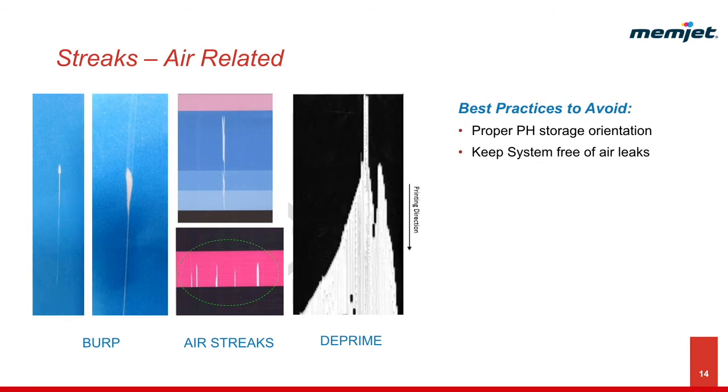When the printhead is stored either nozzle up or if the box is in an upright position, the fluid drains away from its intended position. The printhead dries out and priming is less effective. Recovery for this is usually a second priming sequence.